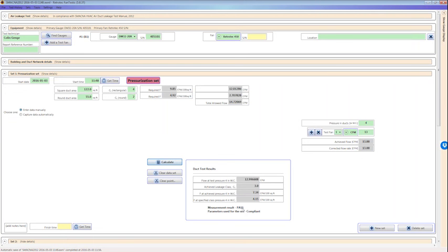Our duct tester flex ends in the equivalent of a 100 millimeter or 4-inch collar. Anything that will go into a 4-inch collar will fit, and we give you one Lindab collar and another device that's 8 inches by 8 inches that can be screwed or taped onto the duct. So you've got 3 different ways of connecting to the duct to make it easy for you.